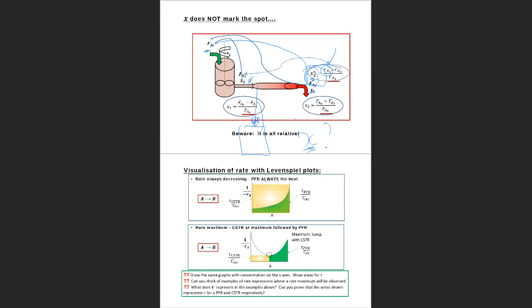I can calculate the conversion, yes, this is a mess, just the incremental conversion over reactor 2, just to find out its performance. Let's say I'm busy optimizing this reactor, and I want to do it with conversion as my goal function. I want to optimize that conversion. Then yes, I calculate the conversion relative to that inlet flow rate.